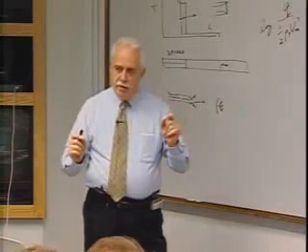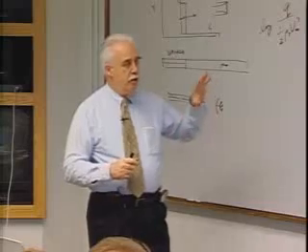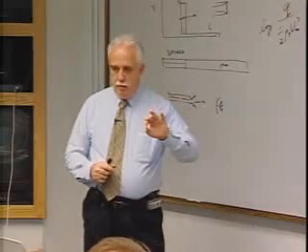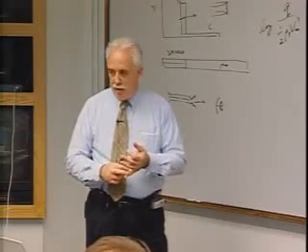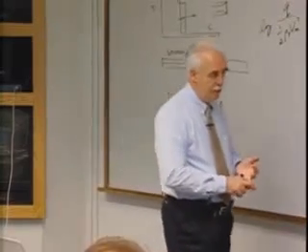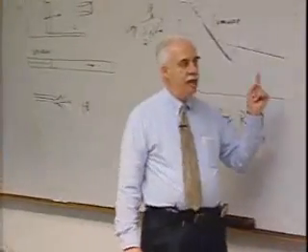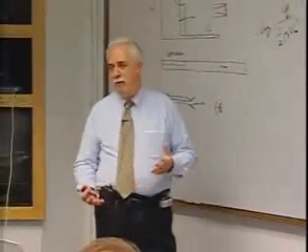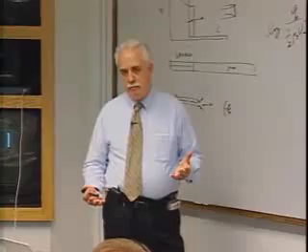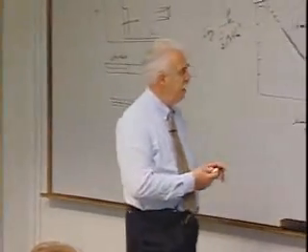It is very valuable information, but you really need to understand what you're doing with that. You can't just take Mach number as the major parameter. It is a significant parameter, but you need to get the Reynolds number, and fundamentally you need to get the enthalpy of the gas. And there's not really a good dimensionless number for the enthalpy of the gas. Okay. There's too much going on for that.